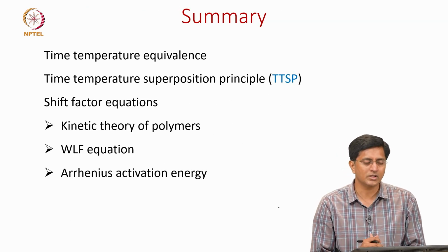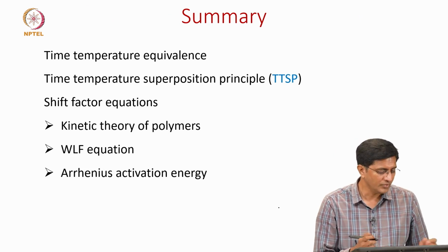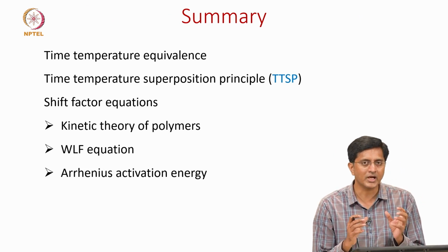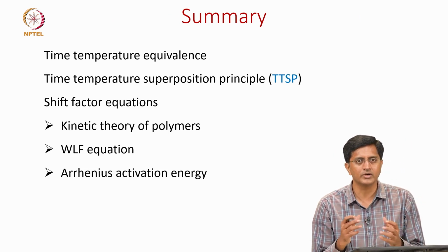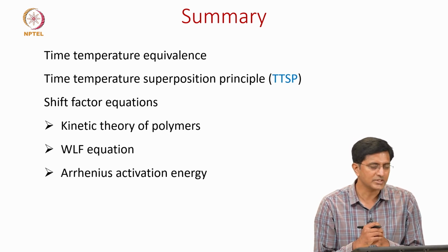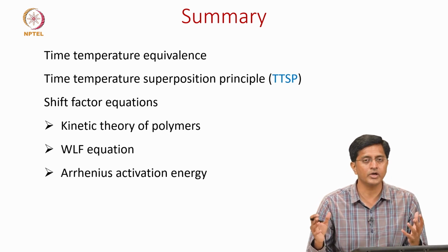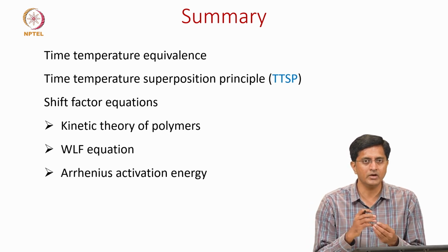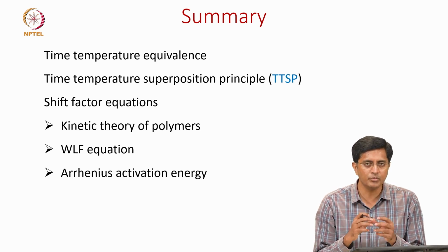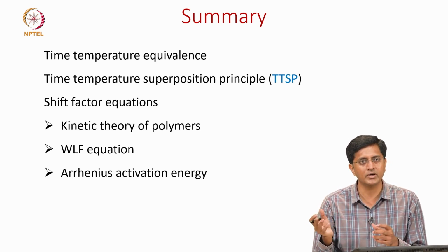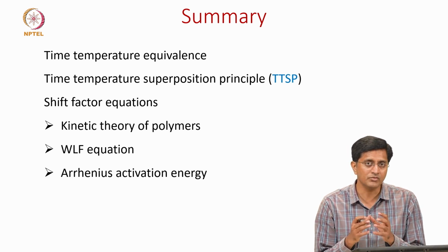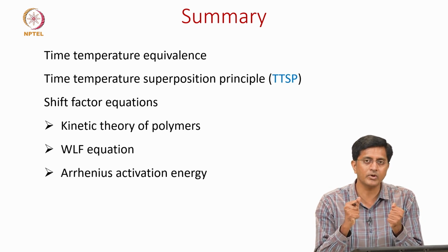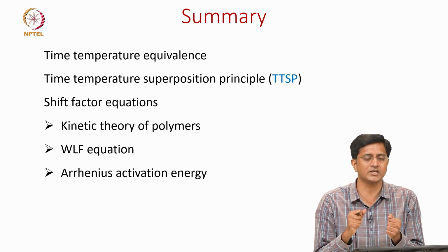So, in summary, what did we discuss in this video? We started by saying both time and temperature have an equivalence, meaning both can be traded off for our requirements. If we are looking for the long-term behavior of polymers, since we are not able to wait for long times, we work with temperatures to be able to predict the behavior at very long times. Actually, we can use the same for very short times, for example, if we want to know how the polymer behaves at less than a second.